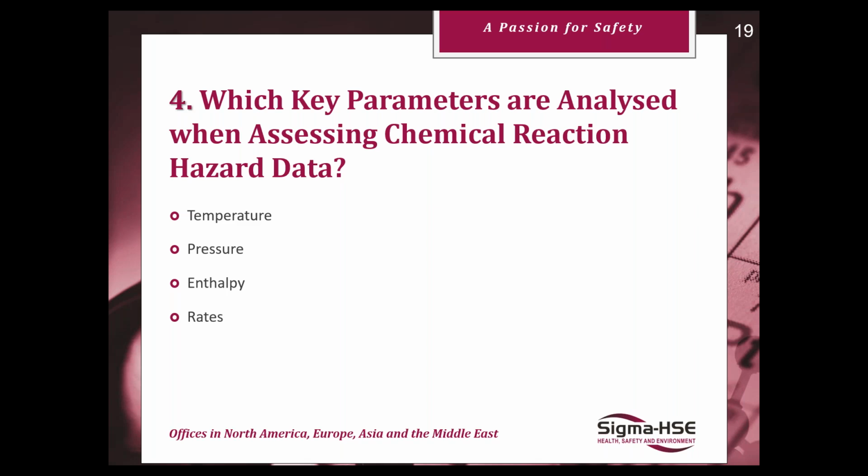We're measuring temperature and pressure. So temperature primarily, we need to test the systems as close to how they will be performed on plant. So what is the temperature set point of your reaction? There's no point us testing a system at 0 degrees when it's going to be operated at 50 degrees on plant. And then also temperature is very crucial for any decomposition onset temperature points. There's a lot of stock put in these onsets for assessments.